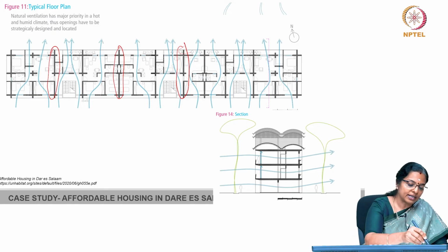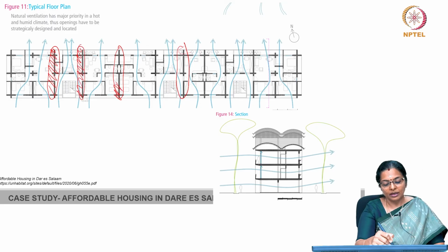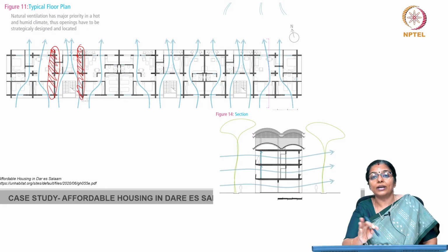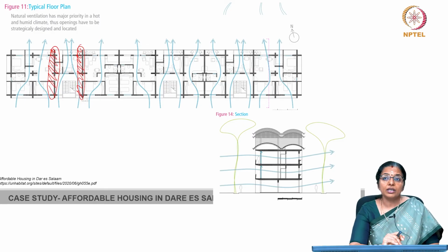So, you orient in such a way that for most of the houses, the western sun gets blocked because all the houses are sandwiched between two houses, and therefore their east and west gets completely insulated. To optimize cross ventilation, louvered windows are incorporated in all the rooms.